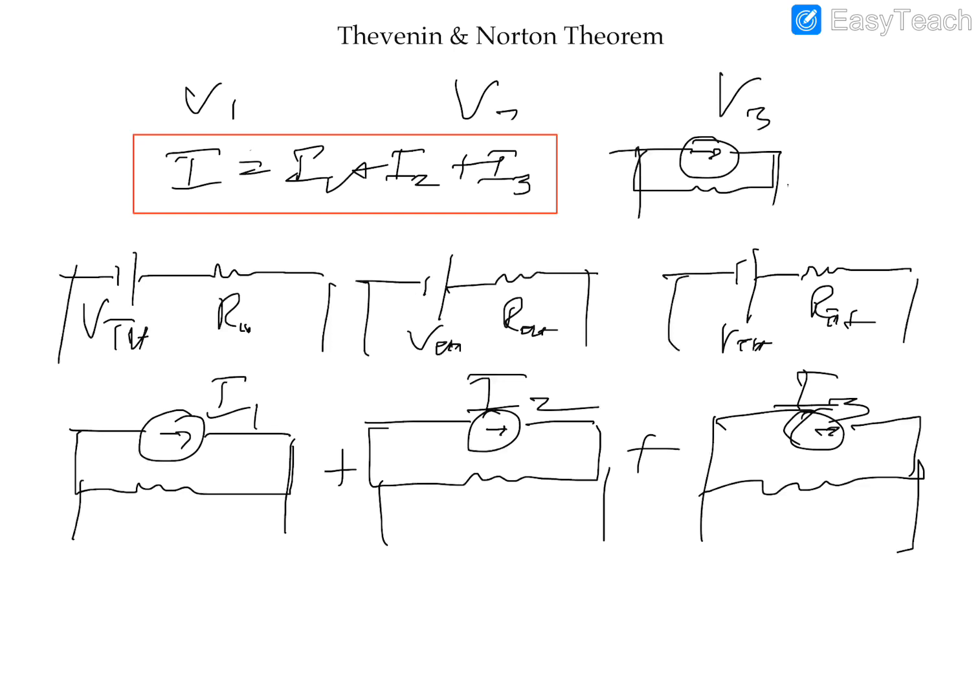Alright. So then you can go ahead and keep the current source the way it is, or convert it to a voltage source in series with the resistance. Now you can say, if I hook up my three generators, which have different capacities, I'm going to get this voltage, which is the Thevenin's voltage, and the impedance offered is going to be this impedance, which is the Thevenin's resistance. So these theorems are very useful when it comes to the real world of power systems engineering.